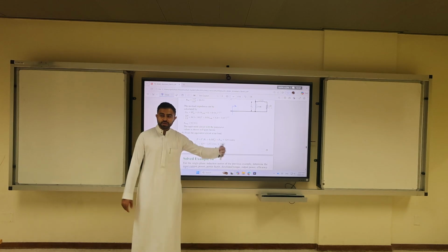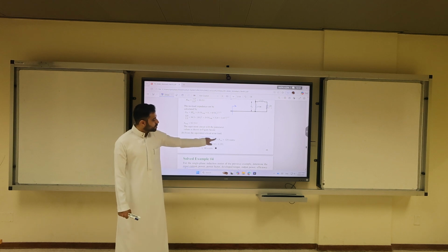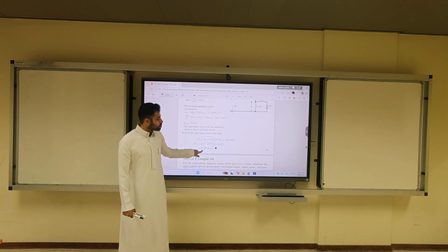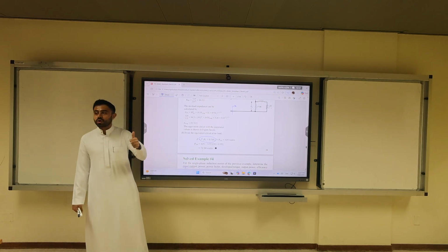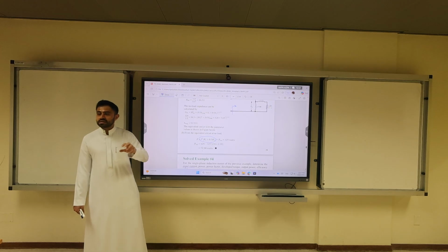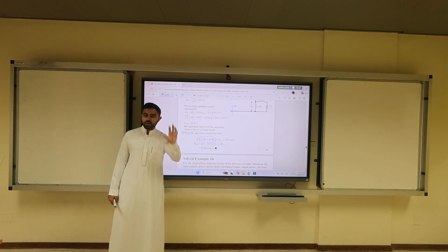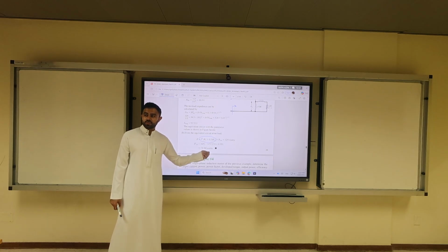So if there is no load, if I just subtract the copper losses, I get the rotational losses, which is 72.90. This is very huge. It includes core losses, magnetization, etc. If the machine has no load, you're going to lose some power other than the copper. This is how to calculate it.